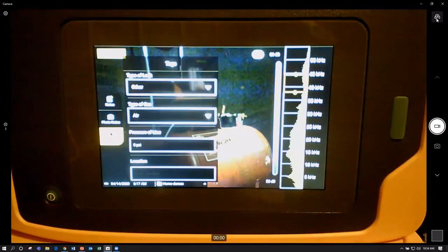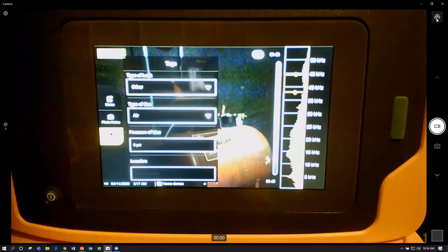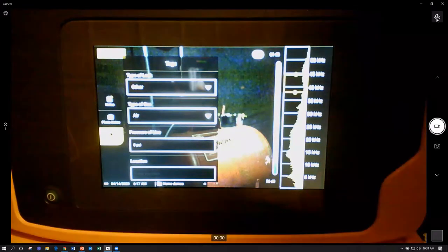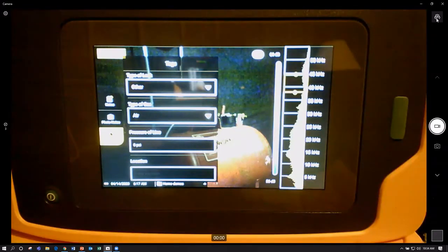Kind of classic way to identify leaks is to put a little tag on them. The guy with the headset on, since he can't show a picture, what he'll do is write out on a tag some information about the leak, and then he'll just fasten the tag right to the tubing or right where the source of the leak is. So if I had a tag, I'd come put the tag right out here, right, on my leak. Let me stop that leak.